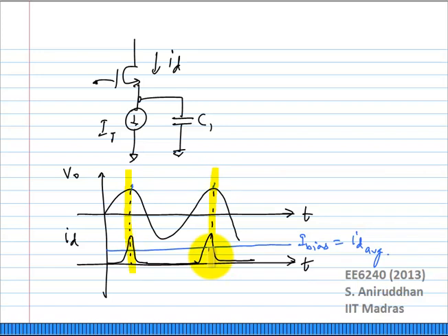Okay, what do you know about noise in an oscillator? If you inject it at the peaks of the voltage waveform, it has very little effect on the phase of the oscillator, right? In other words, such an oscillator has the potential to have very good phase noise performance.